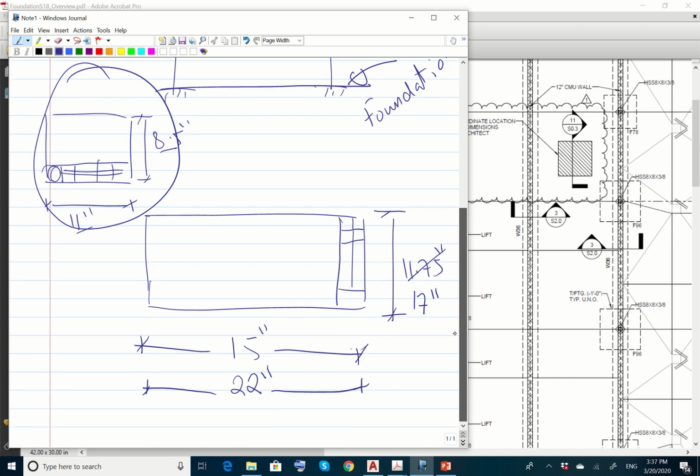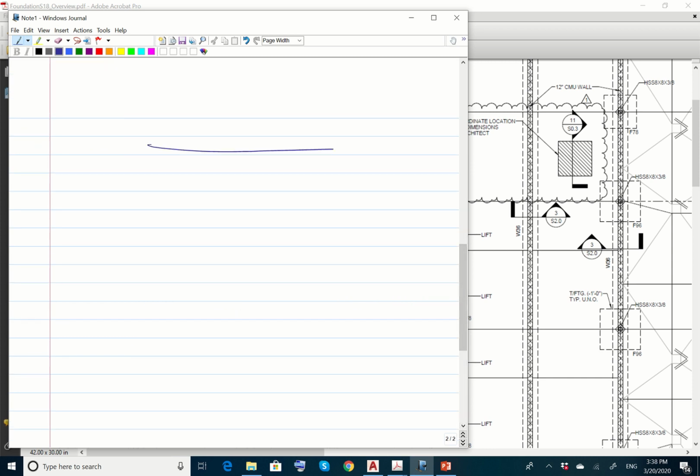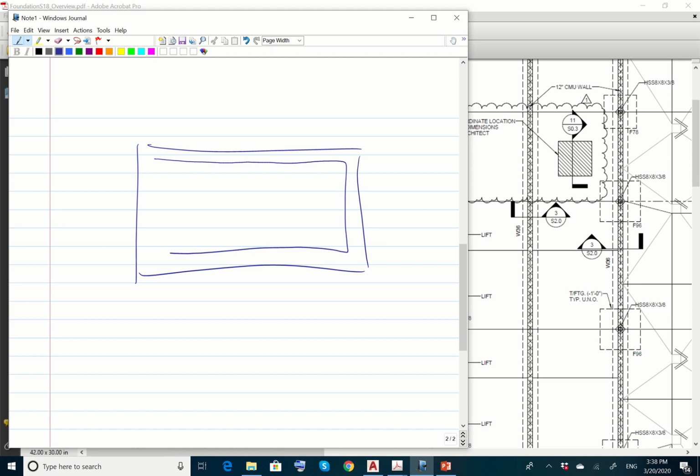So you're going to have the piece of paper over here, and then you're going to create this on the layout. Leave some margin, maybe 1/2 inch from each side, and then you're going to create the table of information on the side, exactly as you did with the other layout on the 8.5 by 11 inch sheet.